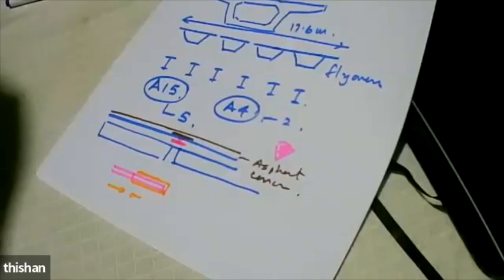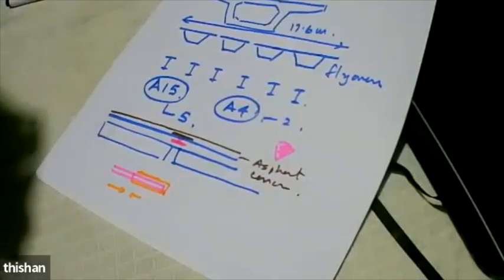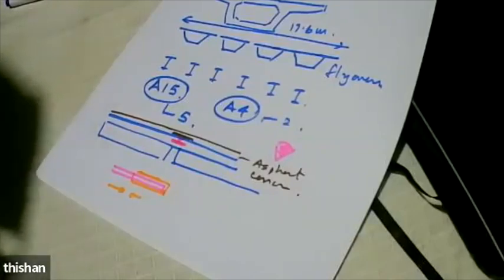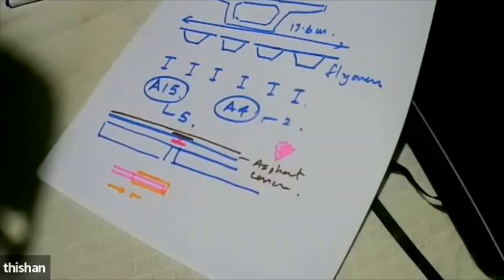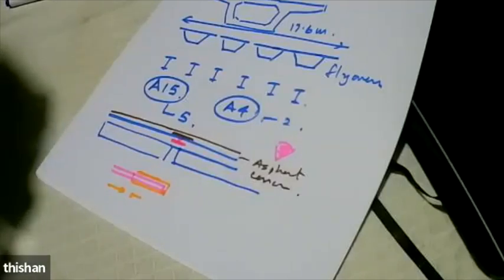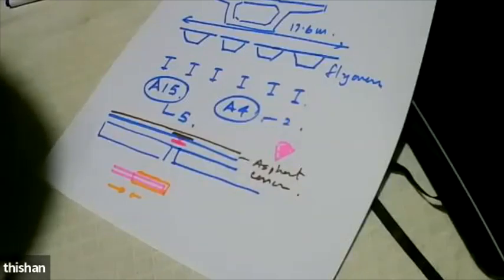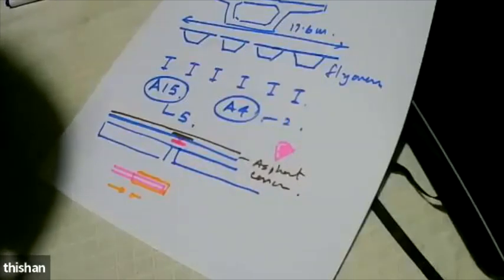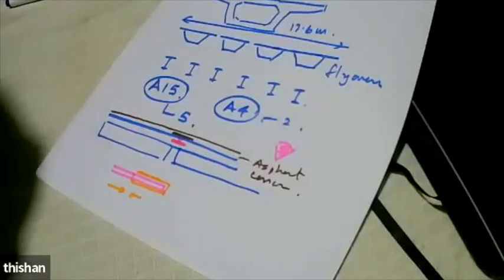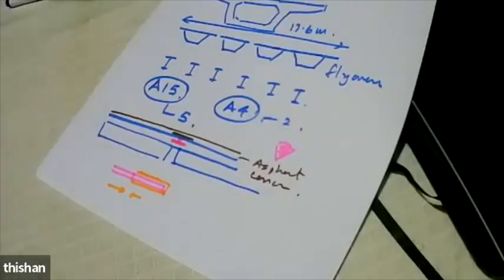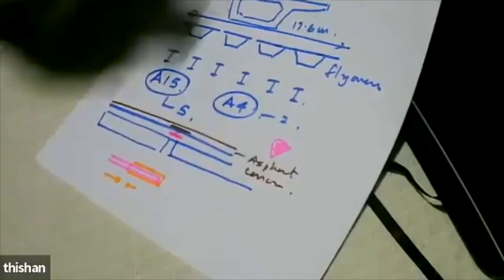And actually, if you do the calculations for Sri Lanka, you will find expansion joints are anyway not necessary, because our thermal movements, the diurnal change in temperature, that is the daily temperature change, is very small. So because of that, even if you don't provide any expansion joint, in Sri Lanka, bridges cannot have any problems, especially the concrete. It's not the steel. The steel bridges can have problems, but concrete bridges will not have any problem. So that is the known situation. So anyway, these have worked well.